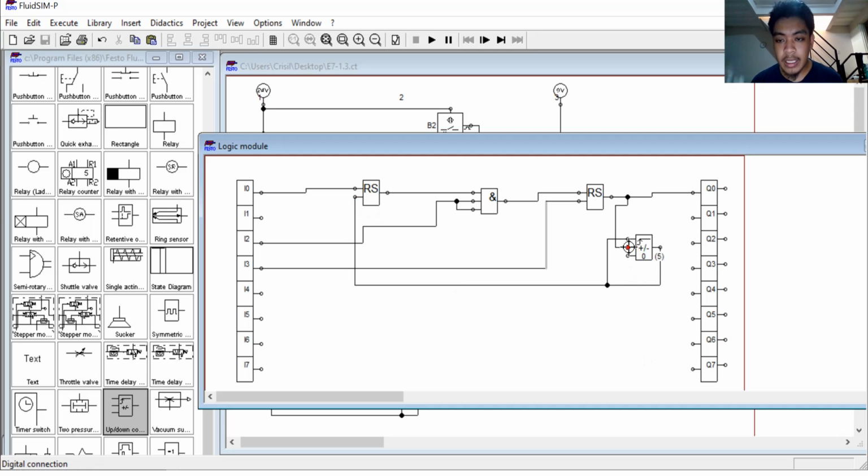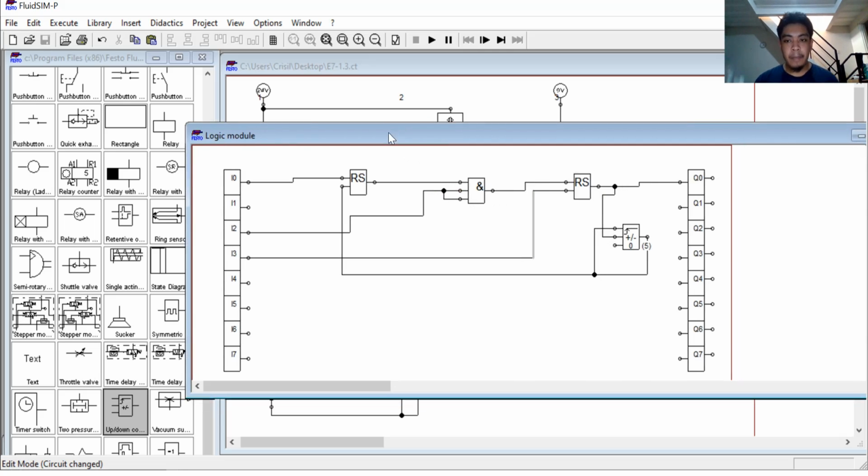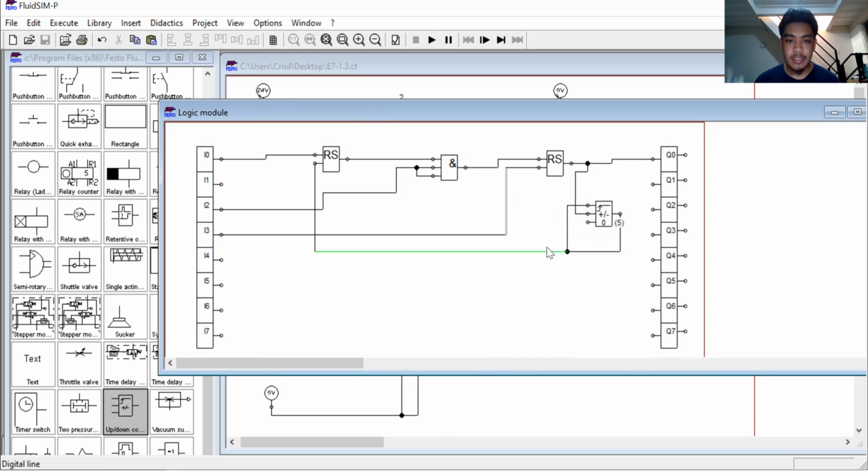Here in the second pin is the count port. This counts the number of times that the piston rod is expanded and retracted. So after 5 times, it immediately resets, resetting here and then halting the operation here. Now here, this is the direction port, so we will not focus much on this, but we'll be focusing on 2 of these ports.